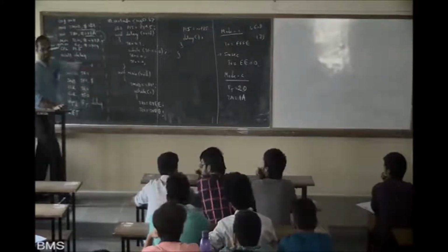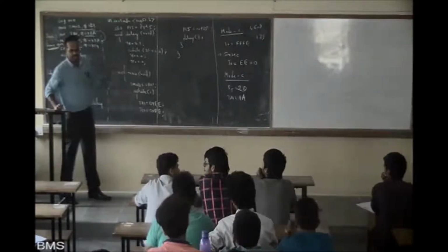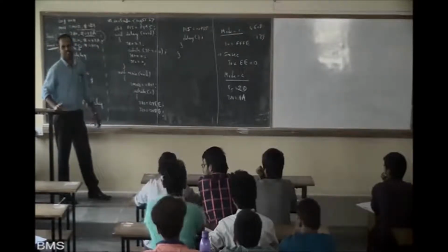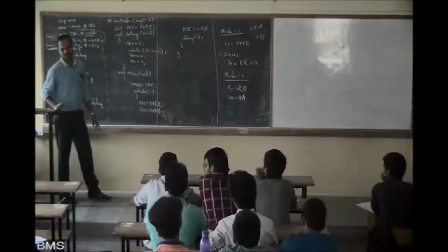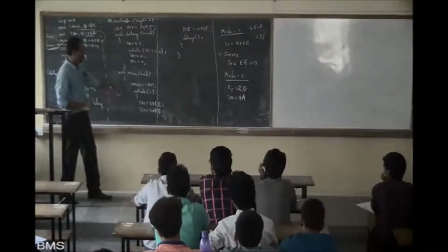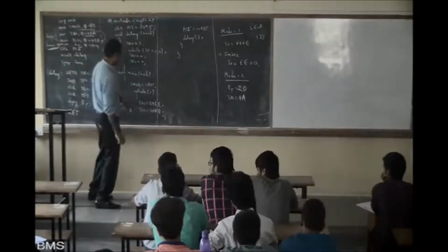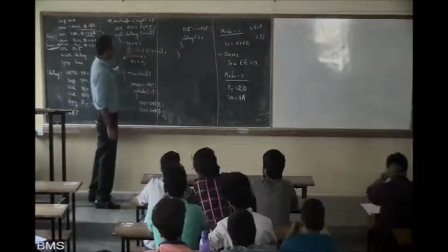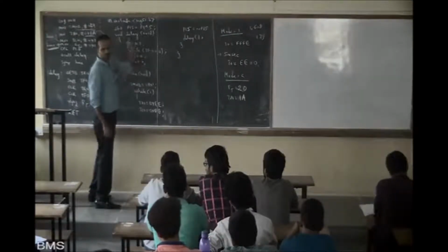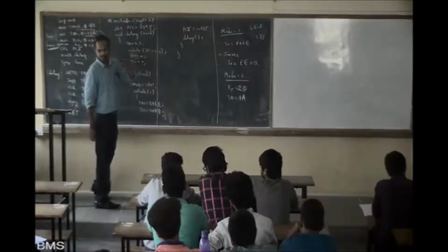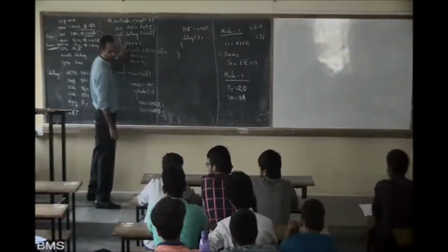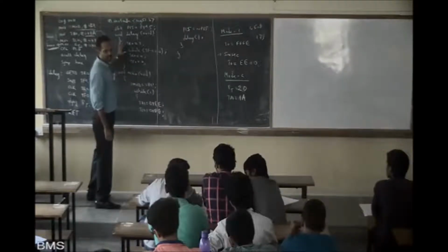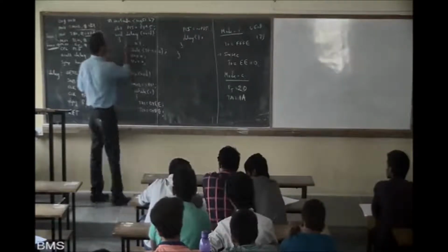Same thing you can write in here. How will you write DJNZ in here? You can use a for loop. Repeat that while 1. Where is DJNZ in this? You should write a for loop and repeat this part of the program for 20 times. Then it should come out. Can you write that part? The for loop will be here.